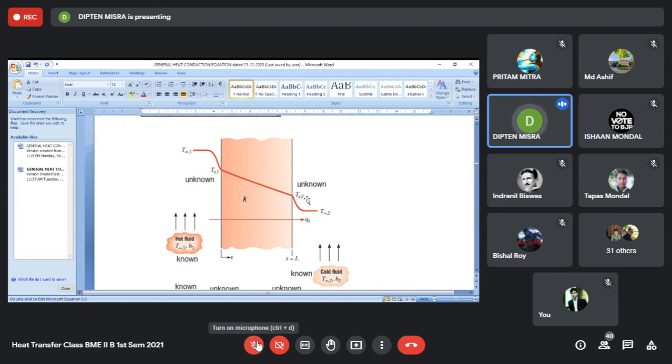So our objective will always be to design a wall in such a way that heat transfer across the wall is at a minimum. So you require to know what constitutes what we call heat. What will minimize the heat loss? What will minimize the heat loss is increasing the conductive resistance of the wall, not thermal conductivity, the conductive resistance of the wall.